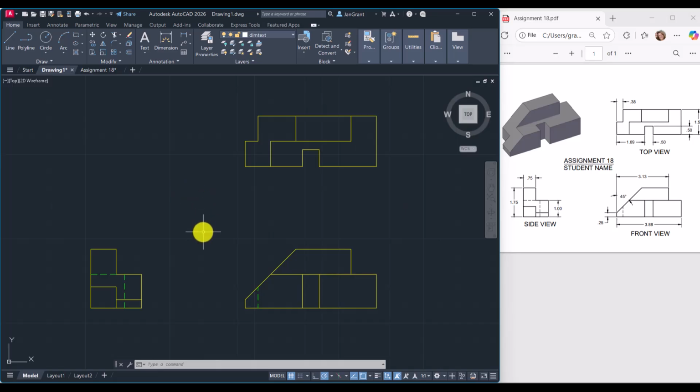I think the only one that might give you a hard time, because we're going to be using linear just like we did before, is angular. Like angular, you're going to need to click on the angled line right there and this little 0.25 line, both those two. Then you can pull your mouse up, and it's okay if you bring it, you probably should bring it a little bit further than where I had it. You see how this arrow gets kind of in the way? You can bring it to there if you want. That would look nice.